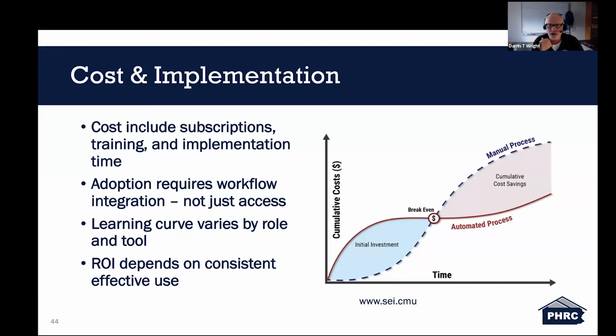Like we talk about air sealing as an industry now. When people first started talking about air sealing, it was a lot of head scratching. People didn't understand what was going on. They're all learning how to do it. We got to get our air sealing down to 3 ACH 50. And through trial and error, the first time we did that looked completely different, the first house, than the 10th house that you did that on. By the 10th house you've done that, you've got the system down, you understand how it works. It's almost all automatic at that point.